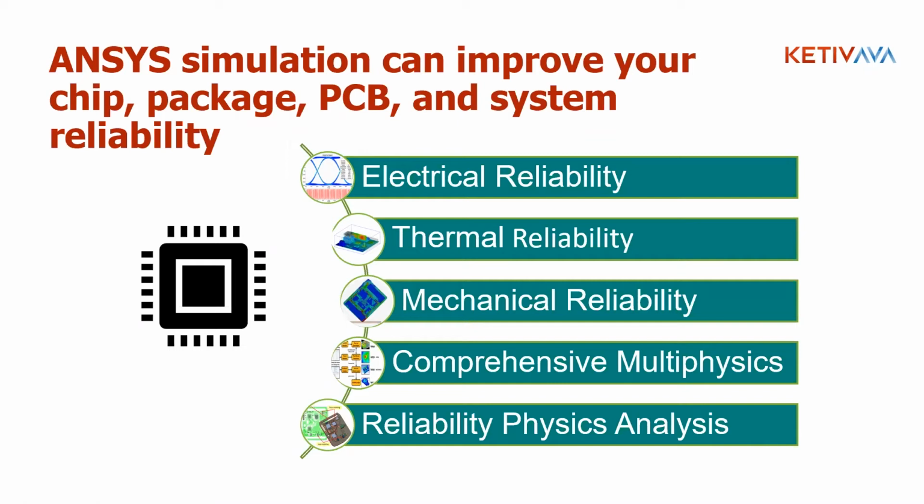Mechanical reliability allows us to look at, if I do a drop test, is the electronic board going to survive? If I'm vibrating it and shipping, is it going to survive? So there are a number of different mechanical reliability tests and simulations one can do. And then you can do combined effects.